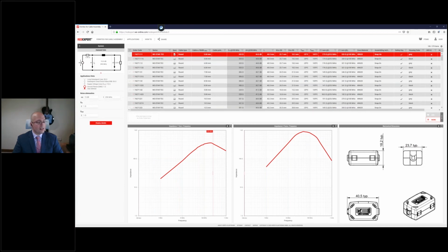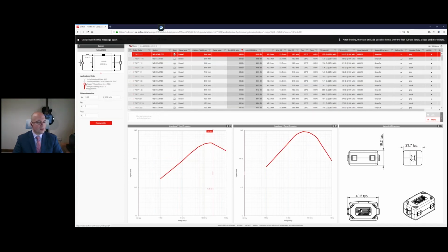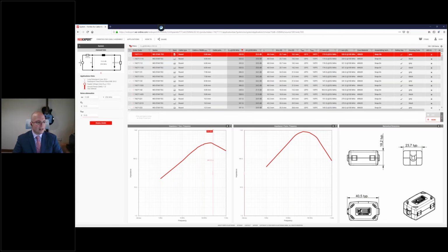Once we are here on the system tool, you remember that we said that it was a DC-DC converter. So I will use this slider in order to select here supply for voltage lines, VCC, 10 ohms. It will automatically set 10 ohms for me on Z in or Z out. If you know the specific impedances, you can just manually type them here.